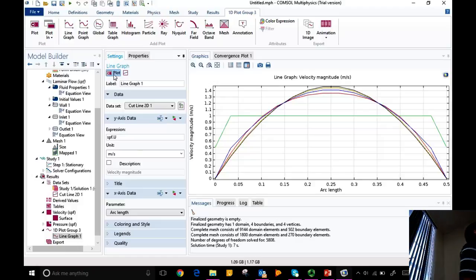Obviously, what does it tell me? The moment I see it, the grid resolution is not good enough. I use the coarse mesh grid. Right? So I get these piecewise linear functions. But eventually, they all collapse on this profile. So the final profile is correct, the parabolic profile. But during the entrance region, there is some sort of inaccurate result. So this one is totally inaccurate. I don't know why that is.